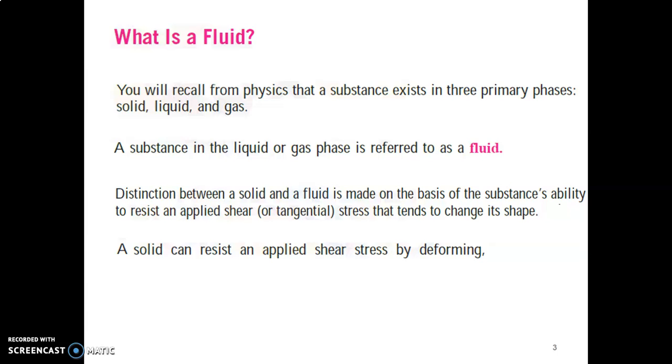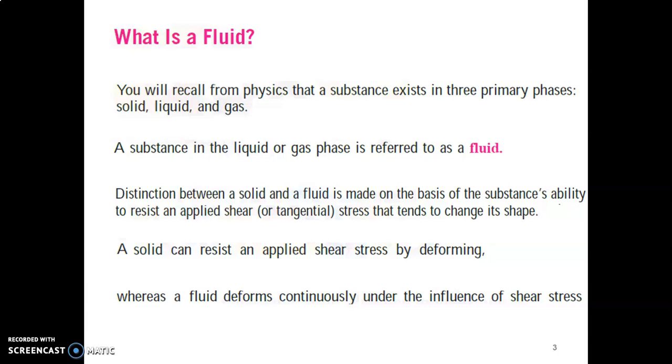Here we can consider that a solid can resist an applied stress by deforming. A solid will deform when we apply a shear stress, but it can resist the applied shear stress even though it is deformed. But in the case of a fluid, it will deform continuously under the influence of shear stress. If you apply a stress on a liquid, it will continuously deform. That's why I mentioned the example: when a liquid is filled inside a container, it will continuously deform until it acquires the shape of that container. That is the meaning we can get from that example. Therefore, the fluid will deform continuously under the influence of the shear stress.